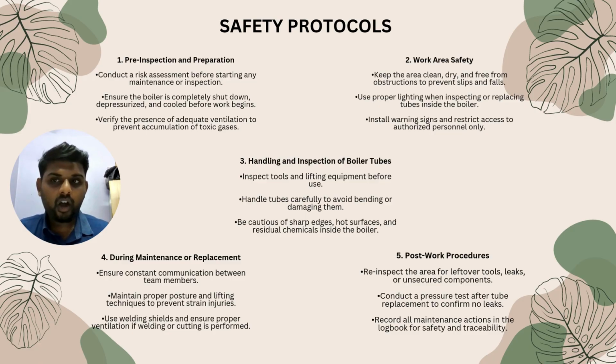Then we need to apply the lockout or tagout, which is LOTO, to isolate all the energy sources from the boiler. Then we need to verify adequate ventilation inside the boiler area. Then we check that all the tools and the equipment are in good condition.